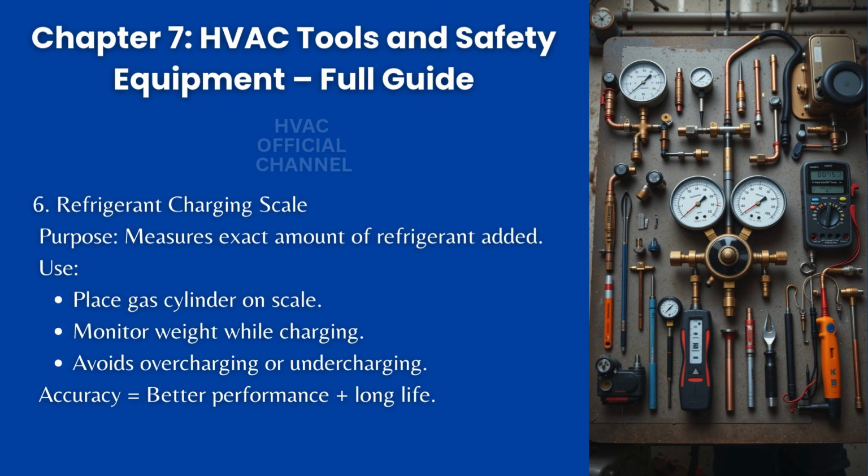6. Refrigerant charging scale. Purpose: measures exact amount of refrigerant added. Use: place gas cylinder on scale. Monitor weight while charging. Avoids overcharging or undercharging. Accuracy equals better performance plus long life.